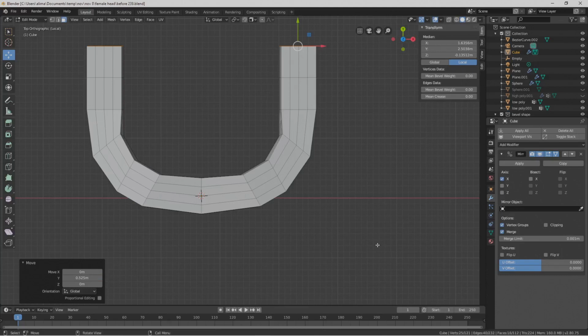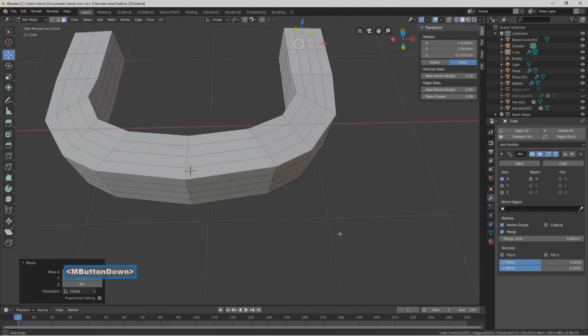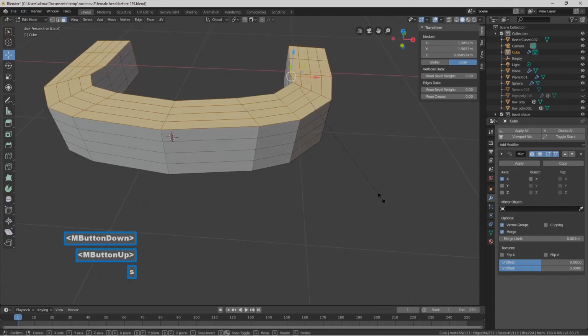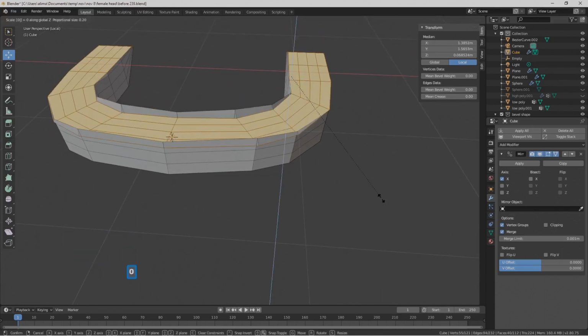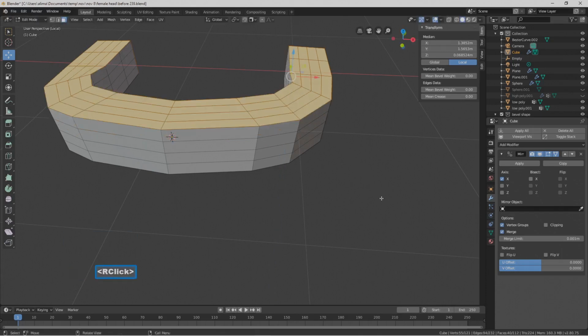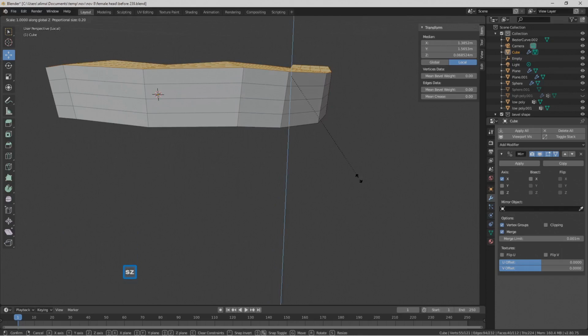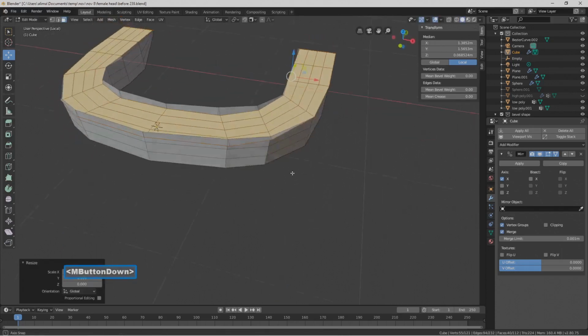Okay, what we're making here is low poly teeth. However, if you want to make more detailed teeth, the same procedure will work. I just press C for paint select. I'm selecting the top of the teeth. I'm going to press S to scale on the Z-axis 0, whoa. That was interesting. S to scale on the Z-axis 0 to flatten the teeth out.